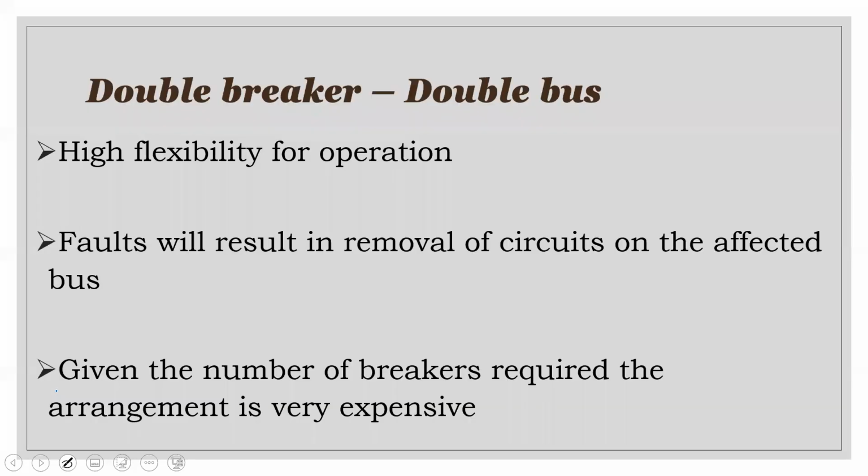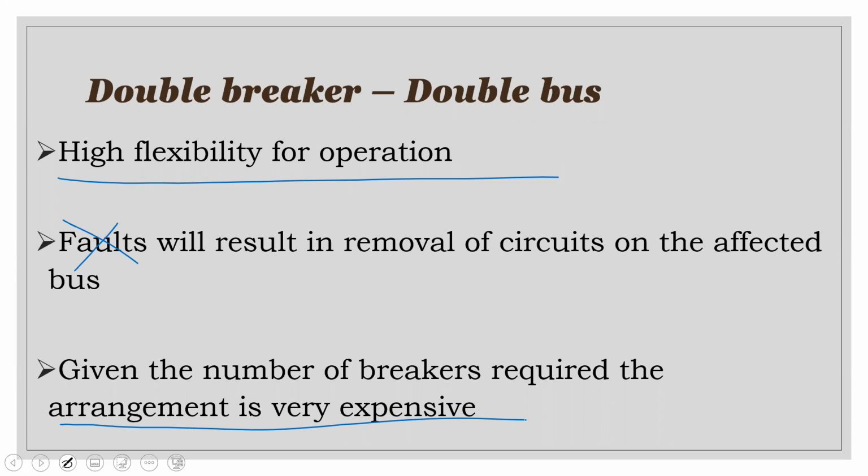All right. I know I only have 5 minutes and I have 3 more to mention. So for your double breaker, double bus, high flexibility. Don't worry too much about this argument, but high flexibility. Very expensive because I'm going to be using 2 breakers for each load. Breakers not cheap. All right. So in terms of the diagram for this one, yes.